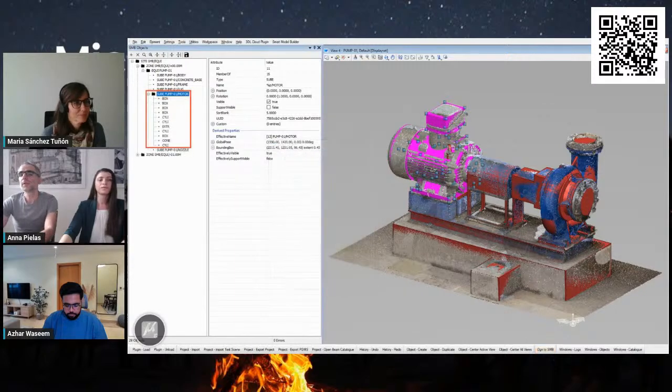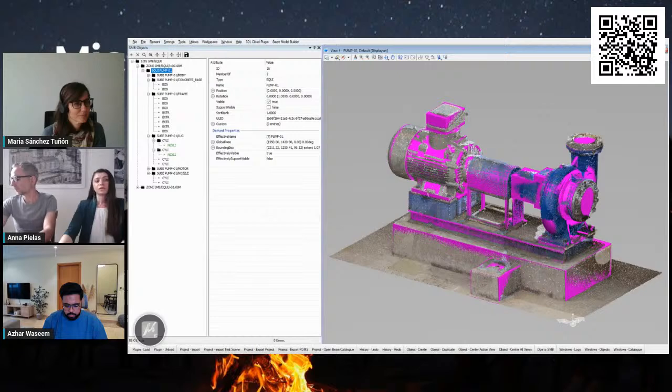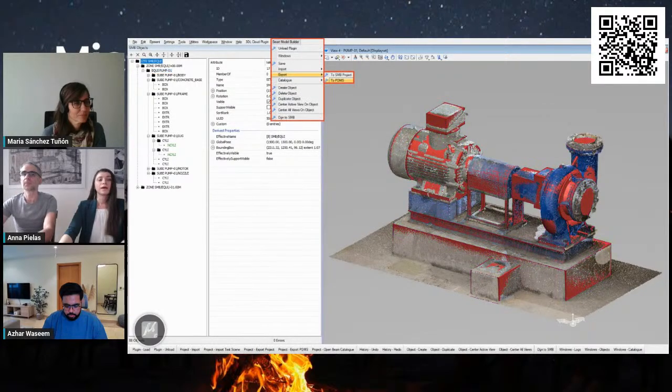I think the important keyword here is the hierarchy, because MicroStation by default just allows arranging models by layers, whereas we enhanced MicroStation within SMB, we added hierarchy. After the whole model is converted from DGN to SMB, now it's time to prepare and export to E3D software.